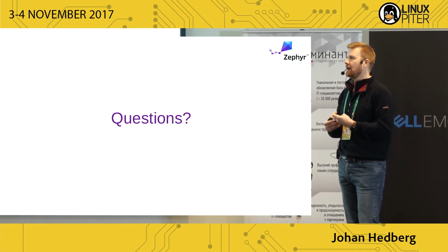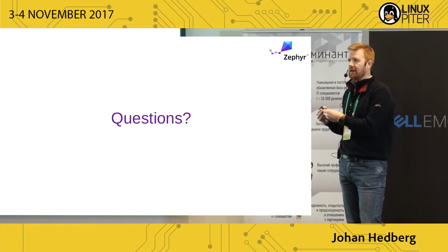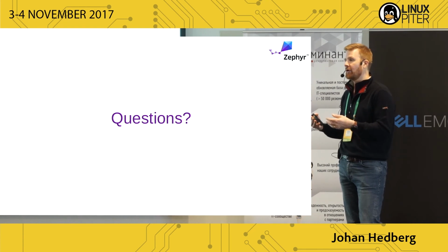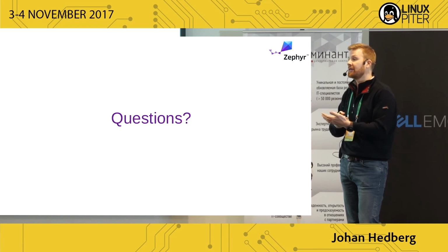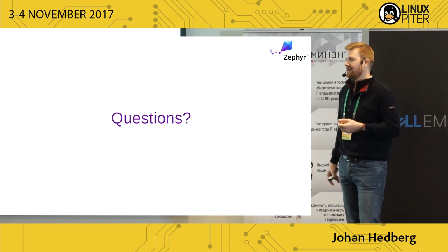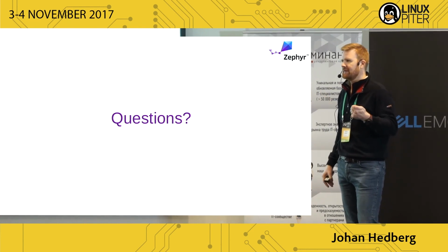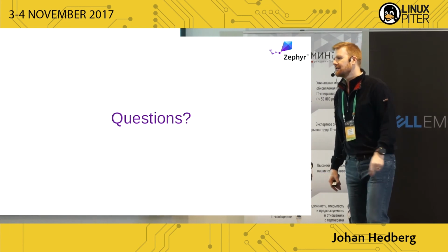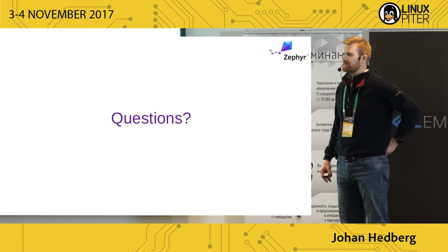You could do it with Zephyr as well, because we have GATT proxy support in Zephyr. So you just need a Zephyr board with sufficient memory to run the full networking stack, the IP stack, and an HTTP server, something like that. You could absolutely do it with that as well. You couldn't do it with 16 kilobytes of RAM, but you could do it with maybe 32, definitely with 64. Thank you. One more.